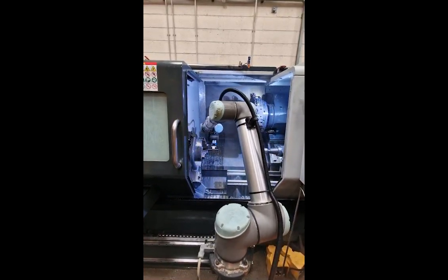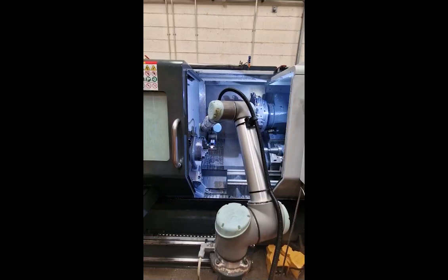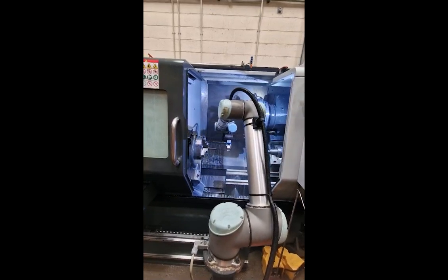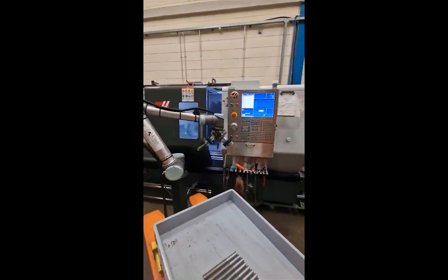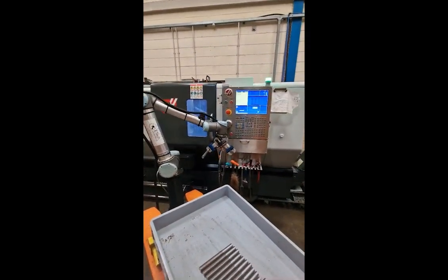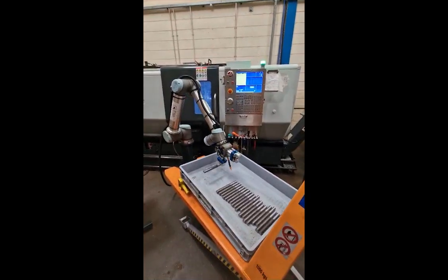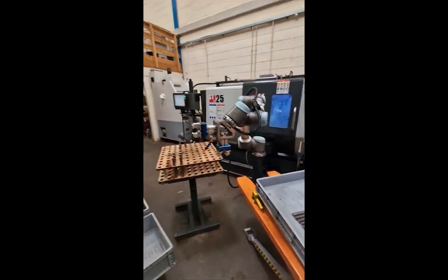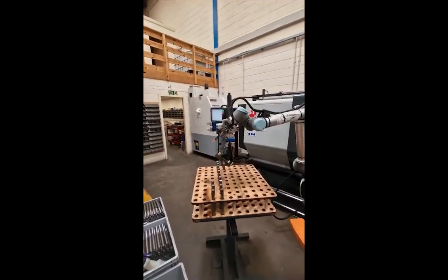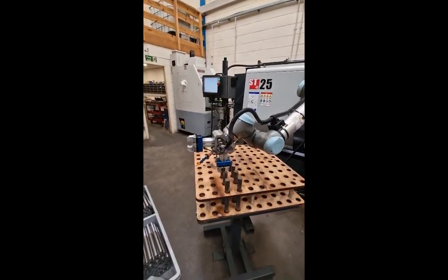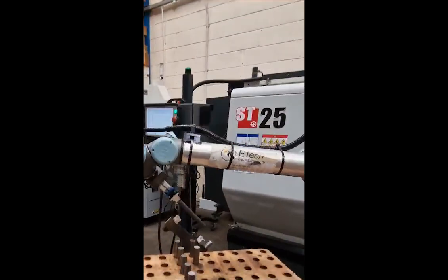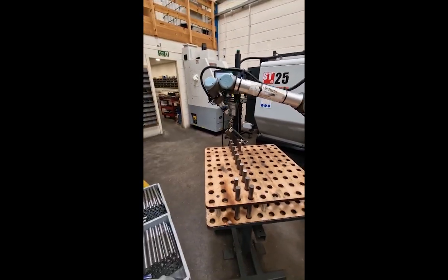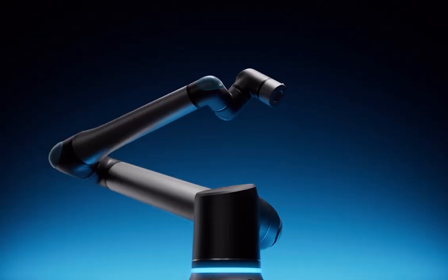It reaches in, takes out the finished part from the chuck, blows out the swarf and the cutting fluid, and then inserts the raw part. The robot will exit from the machine, and on the wrist of the robot there is a small button that forms a thumb. It'll press the start button and that will start the machine. It'll exit and then drop the finished part into a tote and go to the loading table to pick up the next raw part.